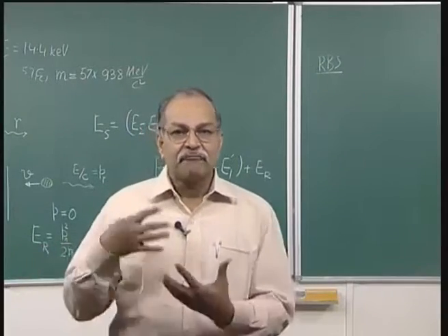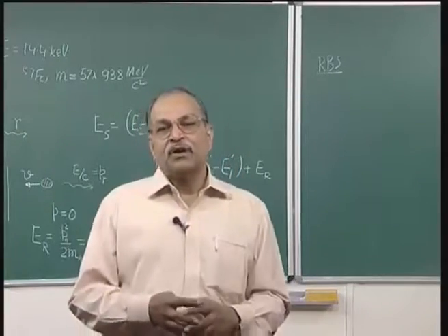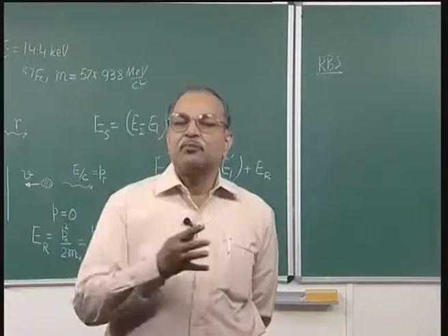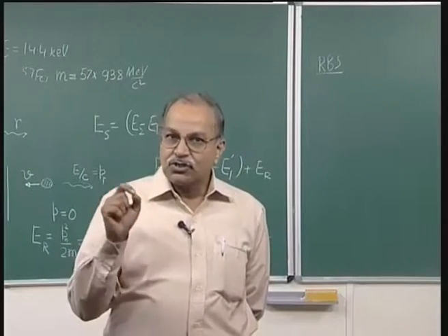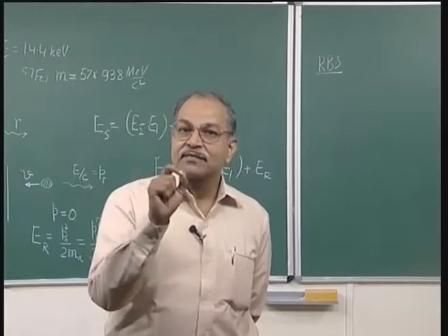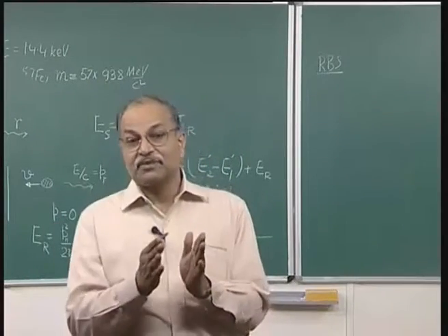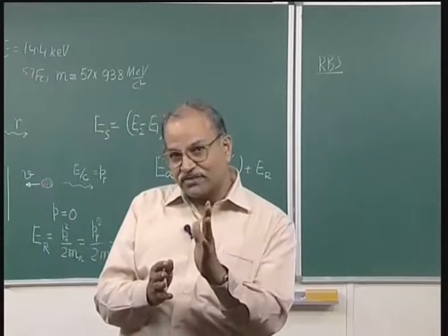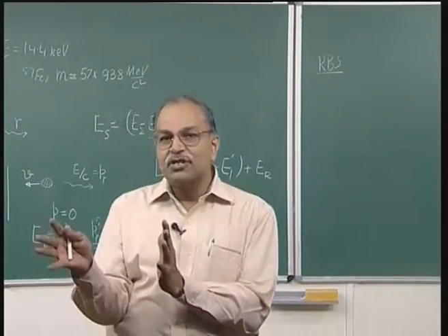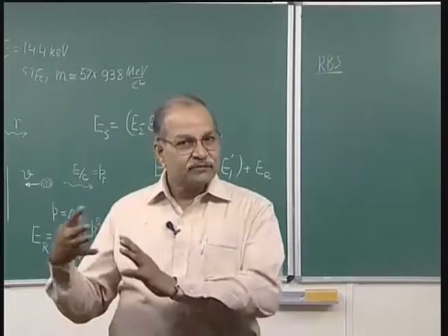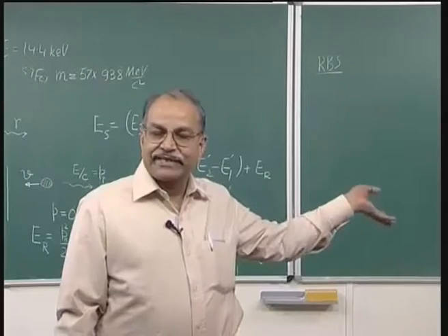So, if you have, say, thin films, or some coating on some substrate, or the substrate itself has, say, up to micron depth, some other elements embedded, and you want to know the concentration of those elements in that sample as a function of depth. So, right at the surface, what is the composition? If you go, say, 50 nanometers inside the material, what is the composition? If you want to get this knowledge, RBS is one technique which can be used.